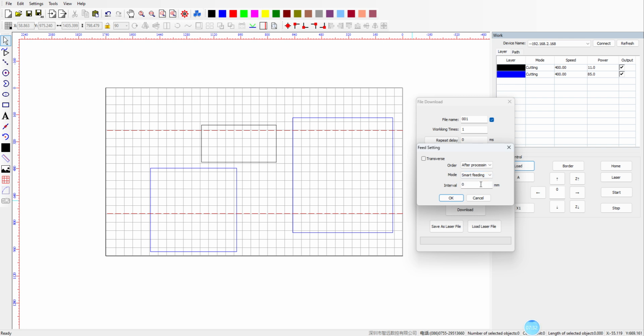Let me show you. Smart feeding means it automatically feeds the distance from the top pattern line to the bottom pattern line. We feed this distance. We don't need to input the real distance. We don't know it; the software will automatically feed the distance. If I click start again, we cut another copy just behind this cutting area and repeat a second time on the rest of the fabric. We can repeat a couple of times directly on the same fabric by the smart feeding distance.